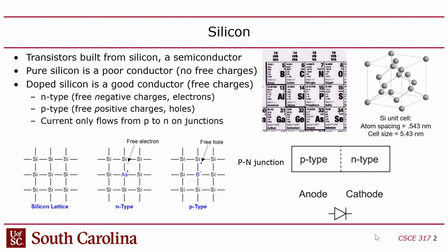So you can build stuff with semiconductors. Like a PN junction is where the P-type silicon is where you dope it with the holes. So that would be the group 3. If you dope with an element from group 3, you're going to get holes as your majority charge carriers, and that's going to create P-type silicon, P standing for positive, and then positive meaning hole, lack of an electron. And then N-type silicon is when you dope with an element from group 5 where you get an extra electron. You get electrons as your majority charge carriers, and that gives you N-type silicon, N standing for negative.